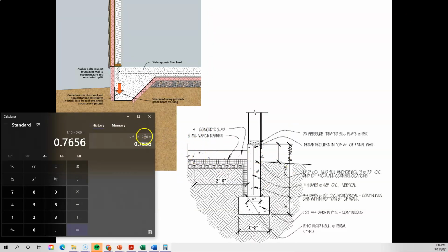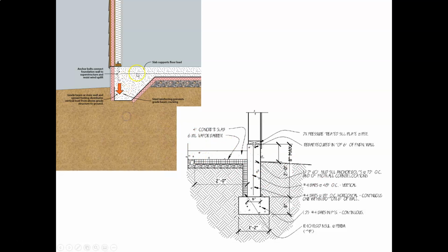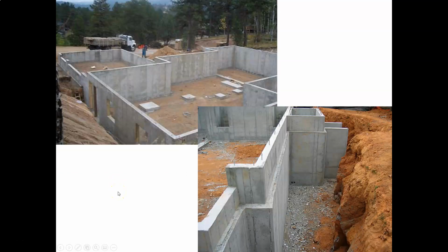So that's a nice looking drawing. That's good information there. Here we have a slab on grade, essentially. And the depth of the footing is, of course, related to the frost line. So here, with no footing, this is probably like a house in Florida or something like that. Here in Philadelphia, we have to get down 3 feet. You know, the warmer the weather, then the more shallow the footings. Okay. All right, and then on top of the footings, we have walls.